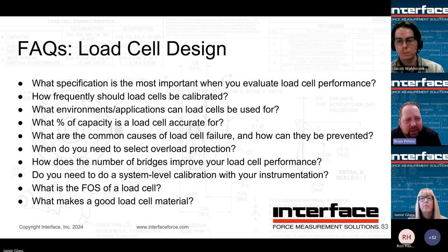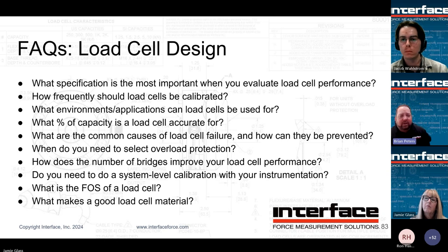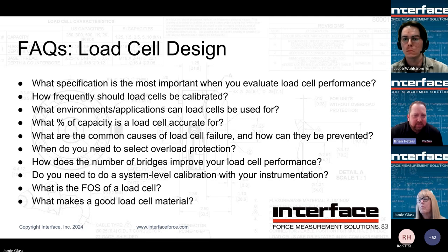So when should you select overload protection, or when do you need it? Well, you want to answer? Basically, a lot of the minis have overload protection, and there's a reason for that, right? It's very easy to overload them, even by hand, if there weren't those overload protection features in there. Brian, you have anything there? Yeah, as capacity goes down, we typically try to offer it. It's necessary. But again, if you've got a test where you're interested in a certain cal range, a very tight test range, but then it still needs to see quite a bit of extra mechanical overage, then yeah, overload protection would be good.